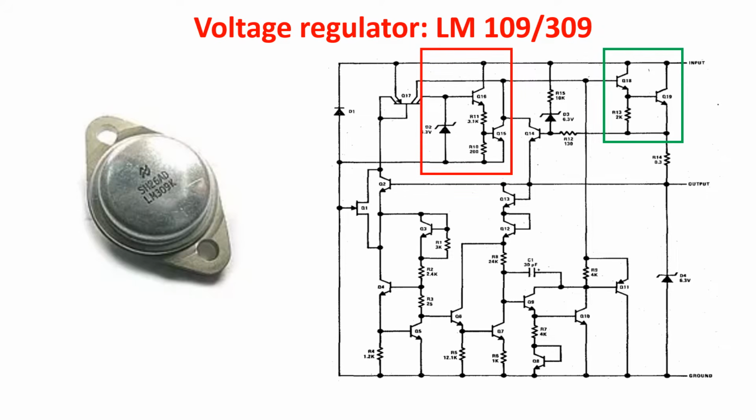In another paper of 1971, New Development in IC Voltage Regulator, Widlar wrote, "Thermal protection limits the maximum junction temperature, providing a constant power limit that protects the regulator regardless of input voltage, type of overload, or degree of heat sinking. With an external pass transistor, there is no convenient way to sense junction temperature, so it is much more difficult to provide thermal limiting. Thermal protection is in itself a very good reason for putting the pass transistor on the chip."